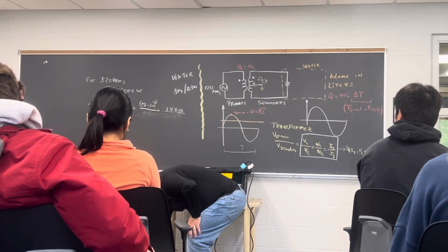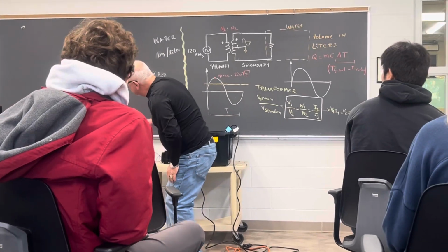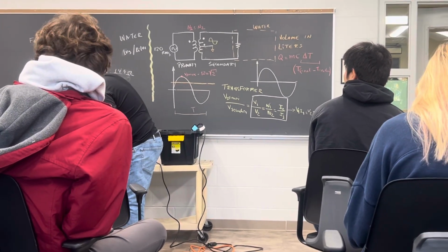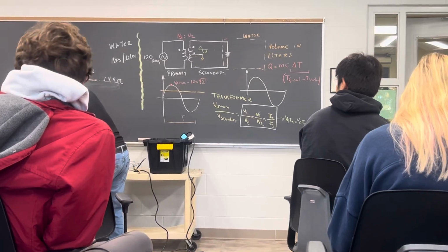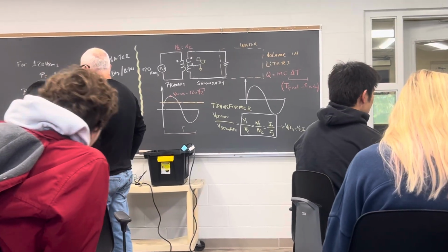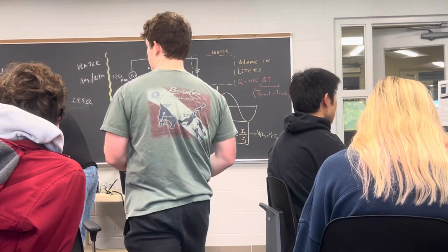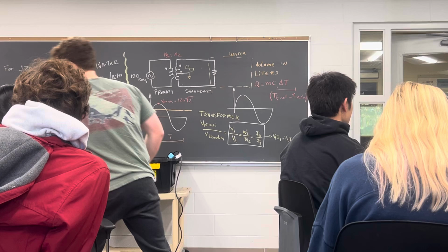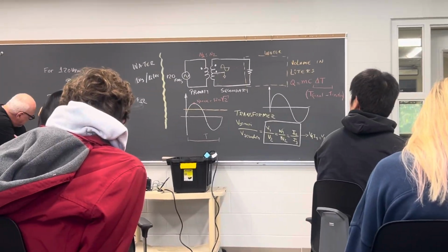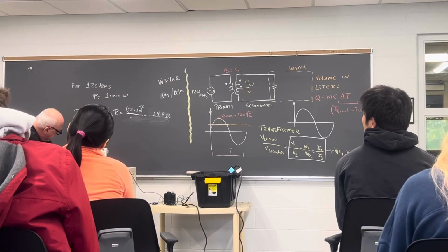I'm going to turn on again. And I should have the voltage there. And I press autoset, which is easier. Great, sine waves there. How do we measure? Well, it says here 48 volts peak to peak.